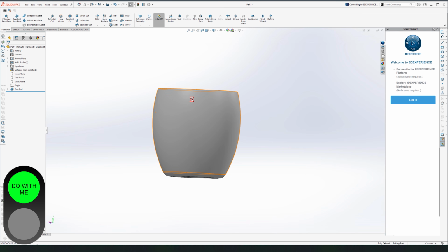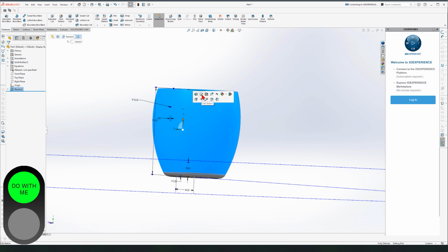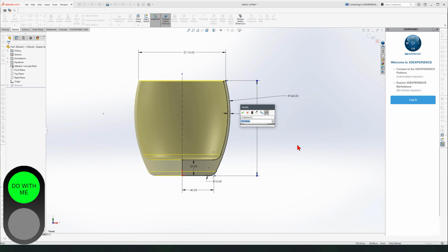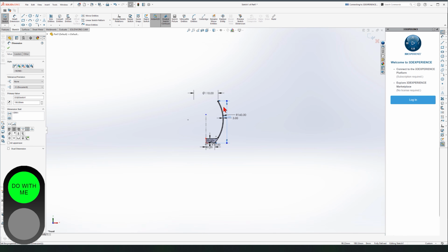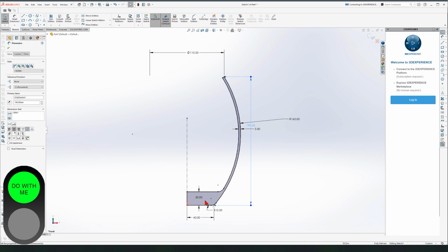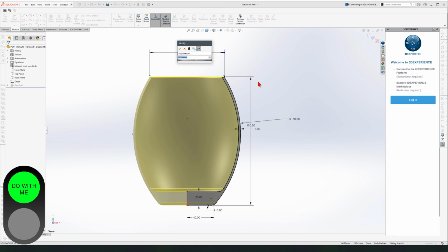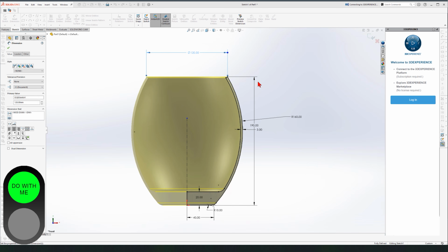So let's click on the model this time. We don't want to go here. I'm teaching you something new. And click on Edit Sketch here. Good. Now let's change the 120 to 190. But then the cap is too close. Let's click on the 110 and make it 120.